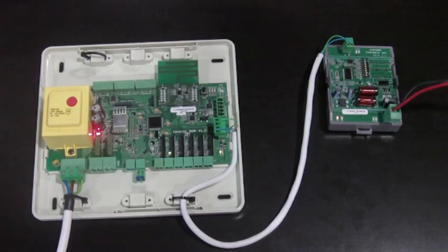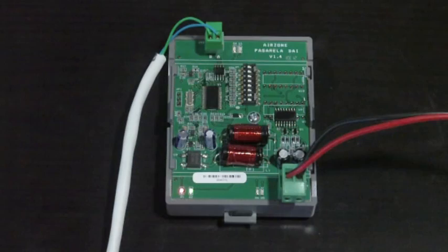The correct working of the gateway can be checked through the indication LEDs. The communication with main controller LED should be blinking on any communication. The communication with the AC unit LED should be blinking on any communication. The power supply LED should be fixed at any time the gateway is power supplied, and the activity LED should be blinking any time the gateway is power supplied.